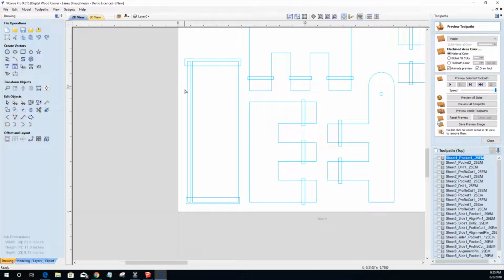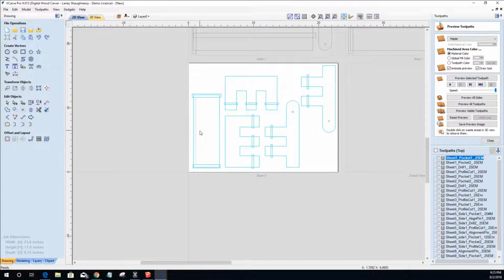We go into node editing and we select this one. Right click and delete the span there. Select this one, right click and delete that span, and then come back and join with a straight line once, twice to close it off, and that finishes that up.